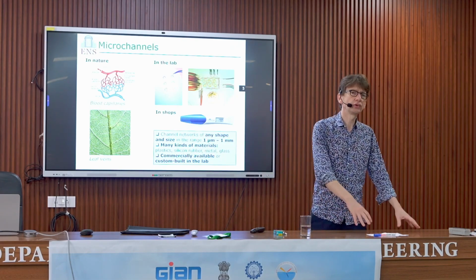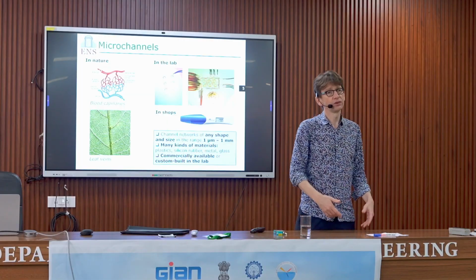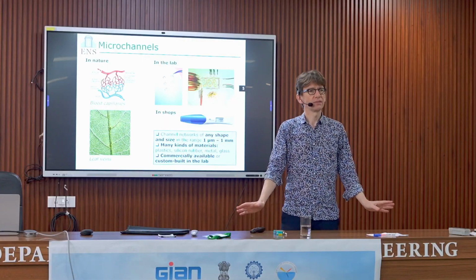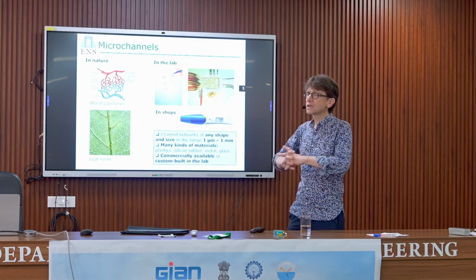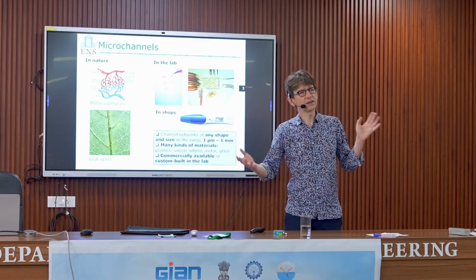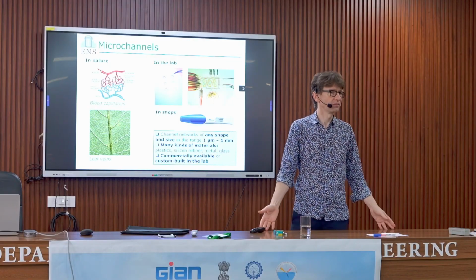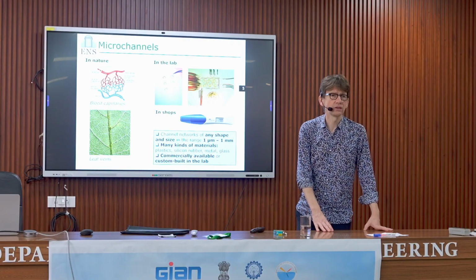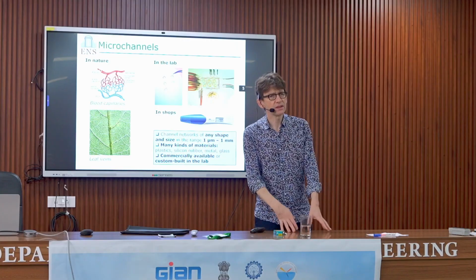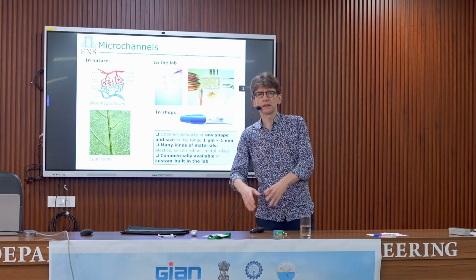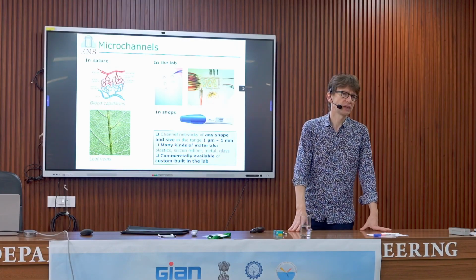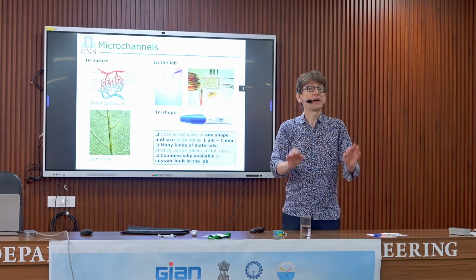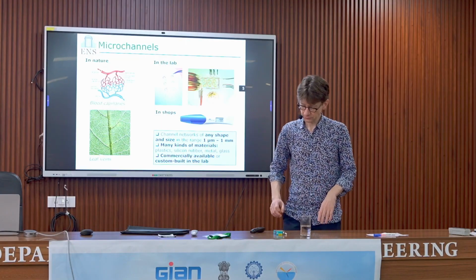Either you can do it, or you cannot, and you ask a colleague, or you buy. So there is no challenge in microfabrication. You can do any channel shape and size you want, basically, and a lot of types of materials. It can be PDMS, a silicone elastomer, of course, but you can also use epoxy, plastic, glasses, and so on. There is no scientific challenge in the fabrication. The challenge is in the manipulation of liquids.